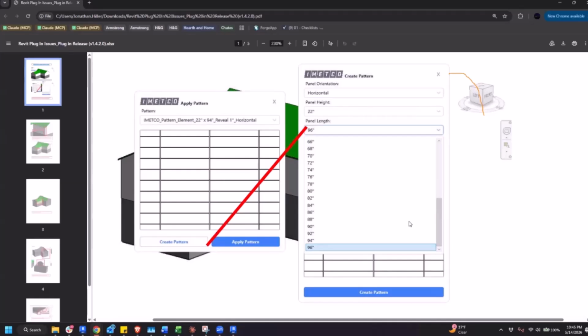If you needed this to go one inch further, you can just grab those horizontal lines and shift them all one inch. That's the way to do it. So that's a temporary fix at the moment? Yeah, that's the only workaround, and as you can imagine, you have to do every row. But if you're in a time crunch and you definitely need this done soon, this would be the only way to do it before the devs get their hands on this, before we determine what the effort is going to be behind this one.